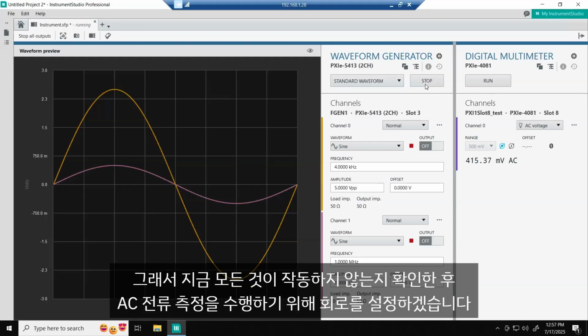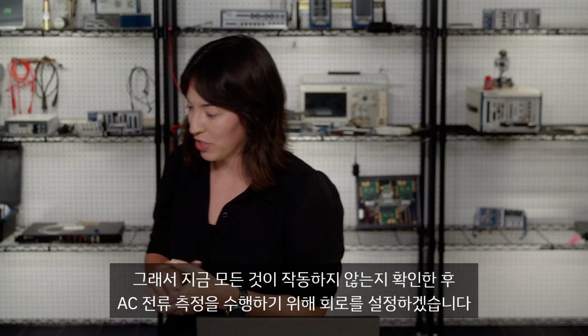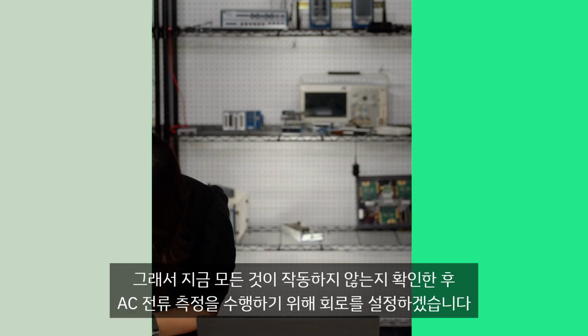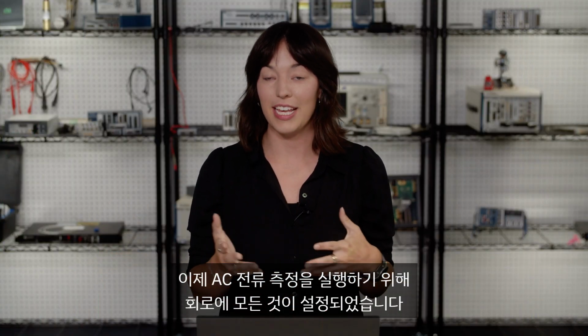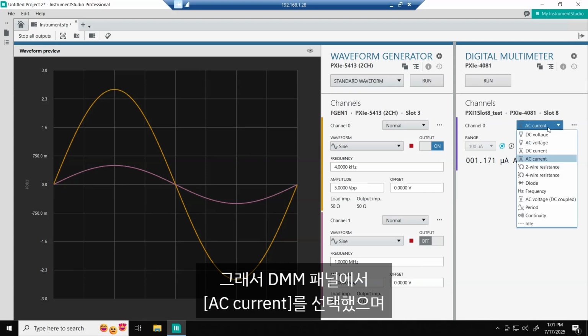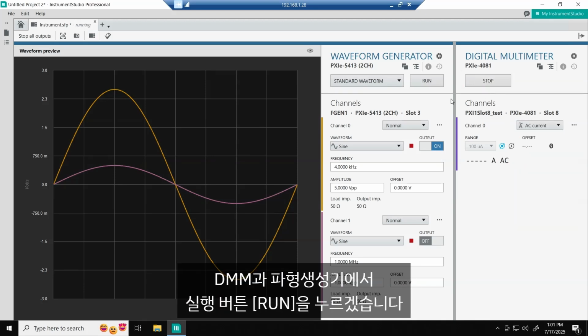I'm just going to make sure all of this is not running, and then set up our circuit to do an AC current measurement. All right, now I've got everything set up in my circuit to run an AC current measurement. I've got AC current selected here on my DMM panel, and then I can press run, and then press run on my waveform generator.